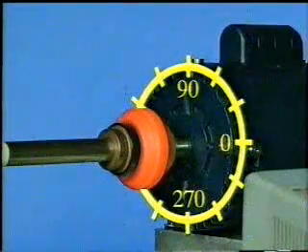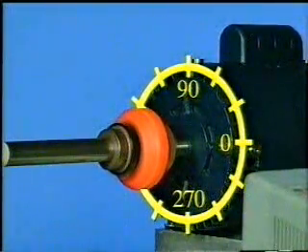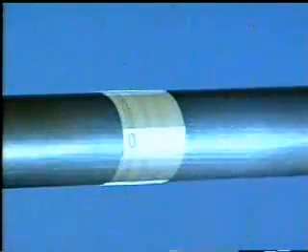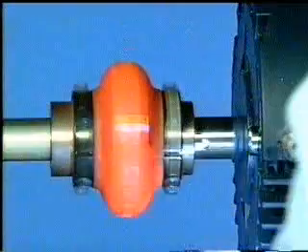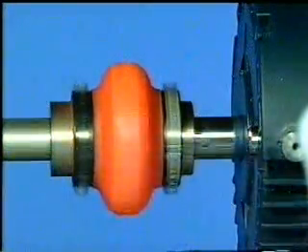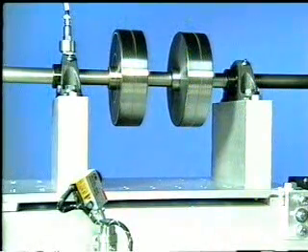When the rotor has a reference mark, then the phase angle must be read from stationary marks from 0 through 360 degrees. When the rotor is marked with the angles, then use a fixed point on the machine as the reference point. Then, as the sensor is used to roam the machine, the phase angle can be read directly from the rotor and the machine, and then manually recorded. Whether you use a strobe or a phototach and analyzer, the rotor must be marked. For most of our examples, we will use the phototach and an analyzer.